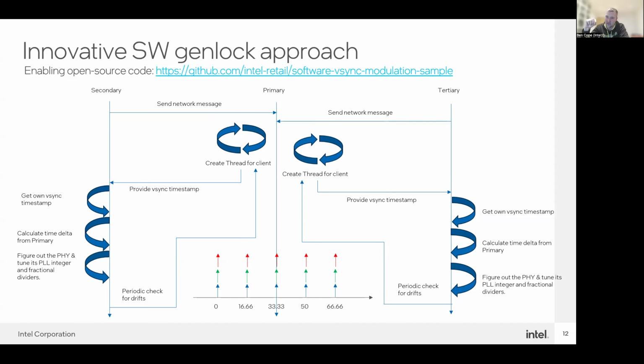The reason Satishwar mentioned that small modification comes down to the speed of convergence. We would typically have a slower speed of convergence than other use cases might have, because we can't move the HDMI clock that quickly. If you move that HDMI clock by too much, it would potentially make the display receiving SoC fall over. So you have to be careful how much you're modifying that as well. That's another related consideration.